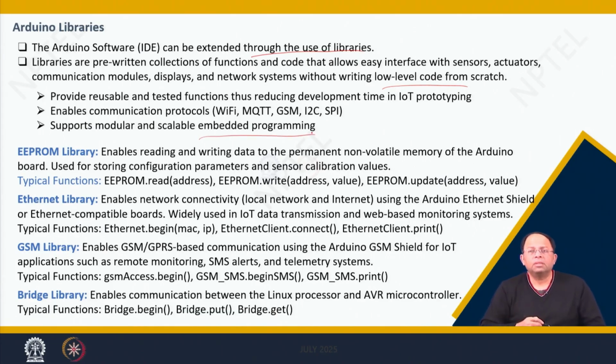But the problem is the memory in Arduino is very small, depending on which microprocessor is being utilized. Like ATmega is very little memory. So if you include a lot of these libraries and all, obviously the size of the program will be much larger. So we have to also make sure that we don't unnecessarily add some libraries, right? So only the ones which are required should be added.